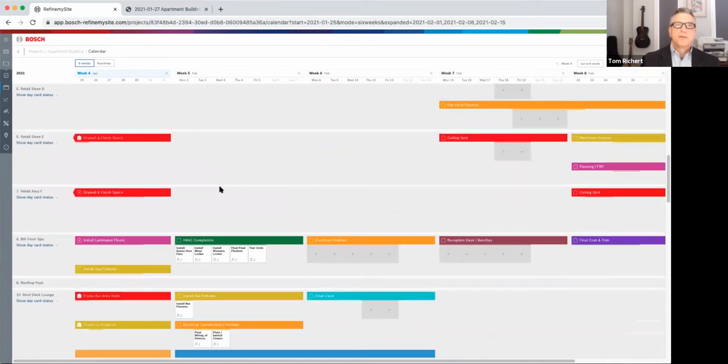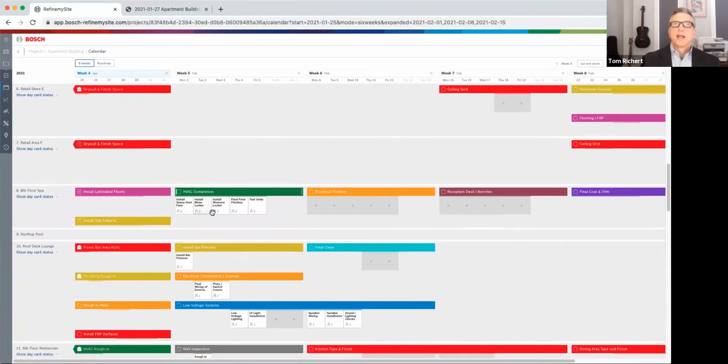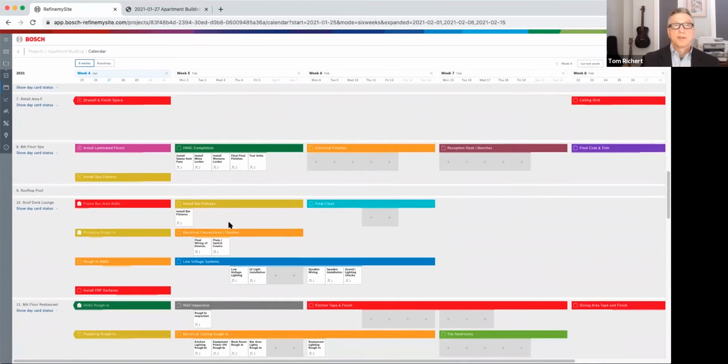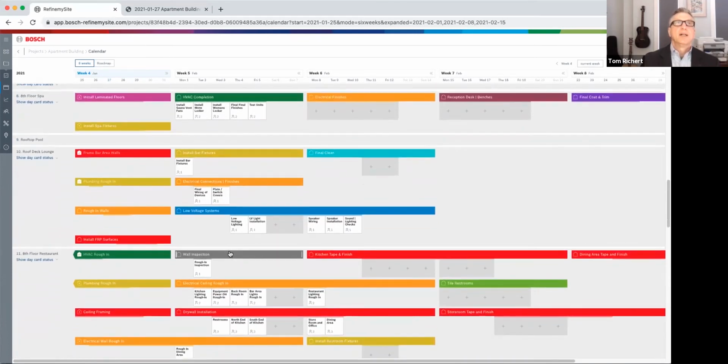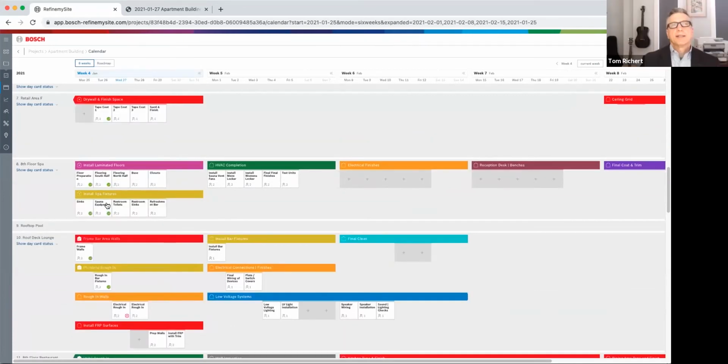at this time of week, if you're getting ready for, say, a Thursday or Friday weekly coordination meeting, you would have the foremen each put in their plan for the day, so everybody can independently work on the cloud-based system and enter their commitments for the week. Just to mention, if I'm a painter trade, I will not be able to create day cards or be detailed on someone else's task. I will only be able to work on the tasks that were assigned to me as a trade. And I'll show you why the day cards are very helpful.